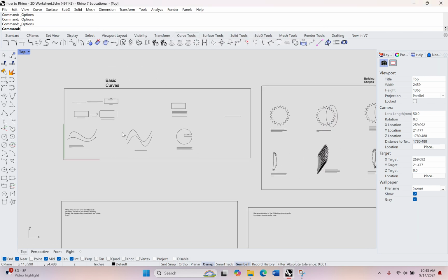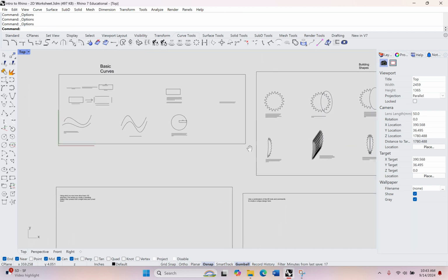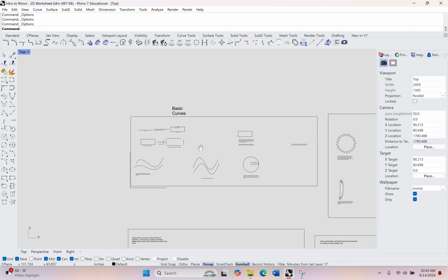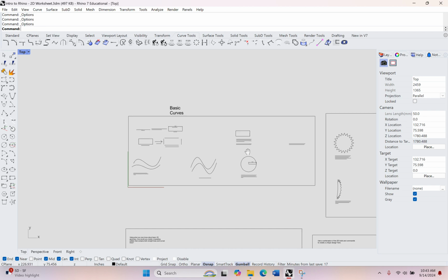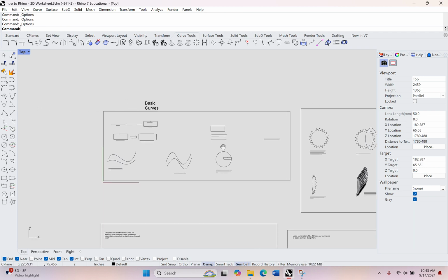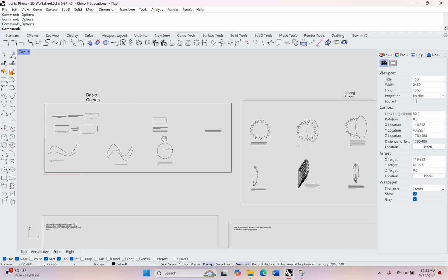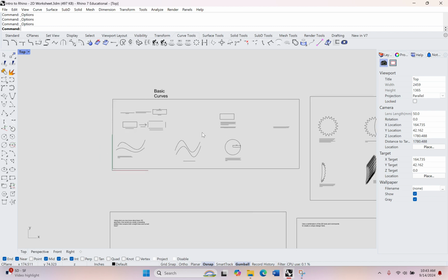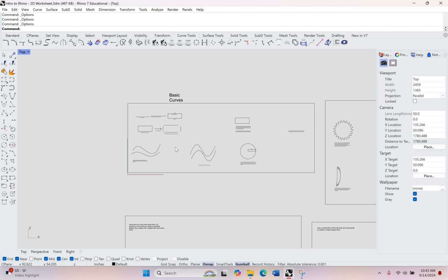All right. Now, navigating your viewport space, your actual workspace here. If you are working with an auxiliary mouse, I think you'll find it's a lot easier to do all of this. It'll be a right click and drag to pan, or basically without changing the cone of vision, move your camera around the workspace.